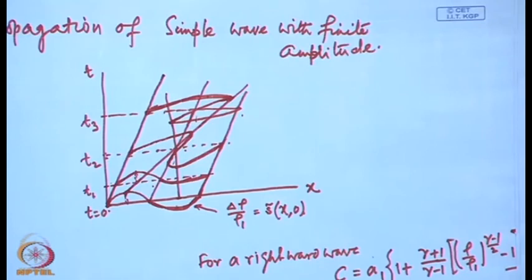and the compression part of the wave will reach a stationary state and it becomes the shock wave. However, the expansion part flattens as it propagates, consequently the gradients become smaller and smaller, and stationarity is never reached and no expansion shock occurs. That is, the expansion part always remains isentropic.